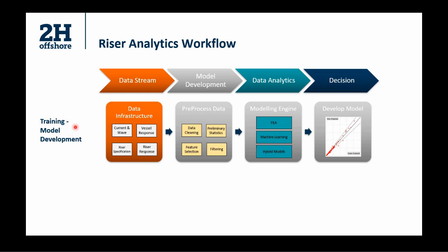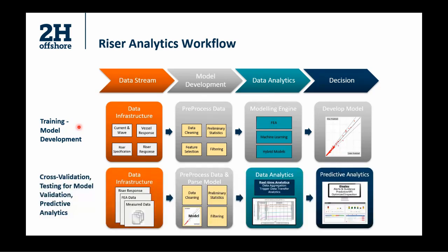The trained model needs to be validated for deployment. During this phase, you have access to both original data and the machine learning algorithm. We feed sea state data in multiple directions to the machine learning model to generate load and stress time traces. From this, we estimate, for instance, fatigue damage and assess it against some form of key performance indicators for integrity management applications. This is the predictive analytics that we talked about.